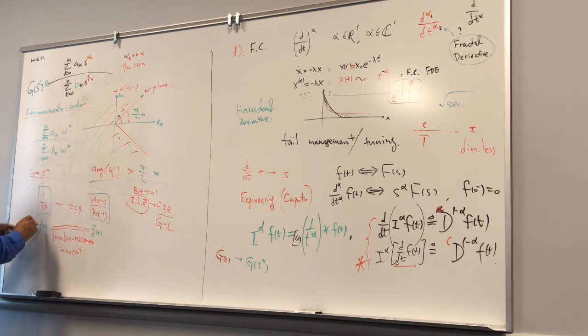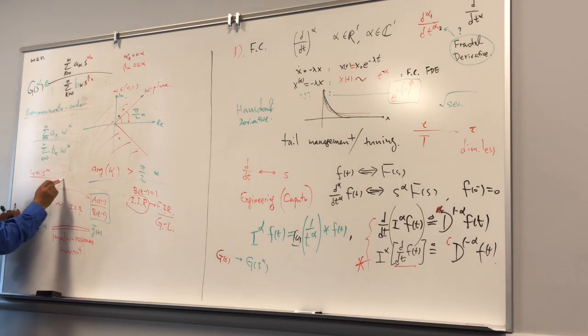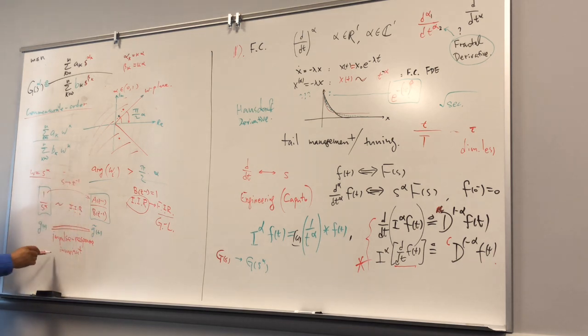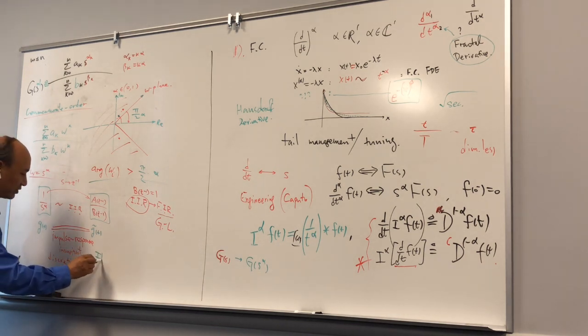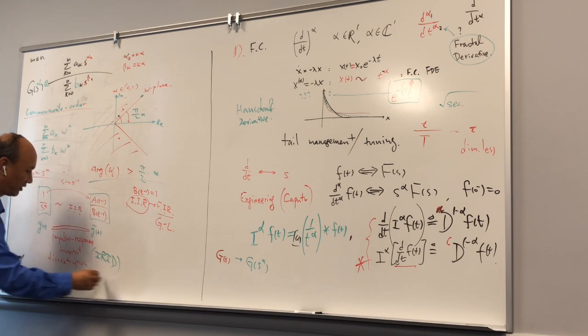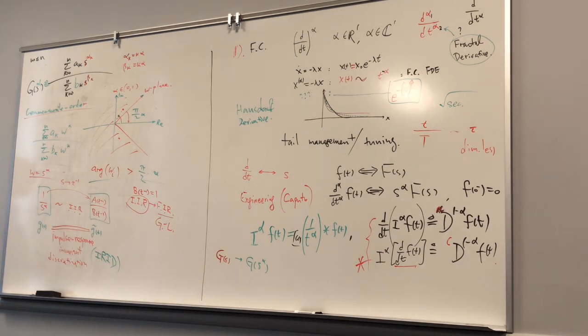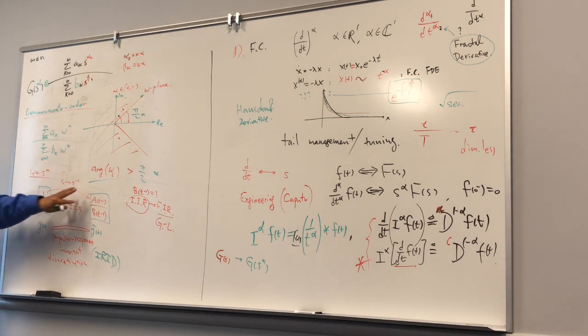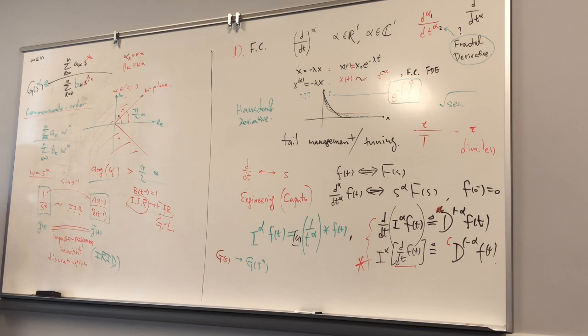Then we turn this one into, this is like S to Z, right? So this is called discretization. I invented this one, called the impulse response invariant discretization method. You guarantee that after you do the approximation, this impulse response and the analytic impulse response are the same. They didn't change. That's very good, isn't it? Consider that a good approximation.